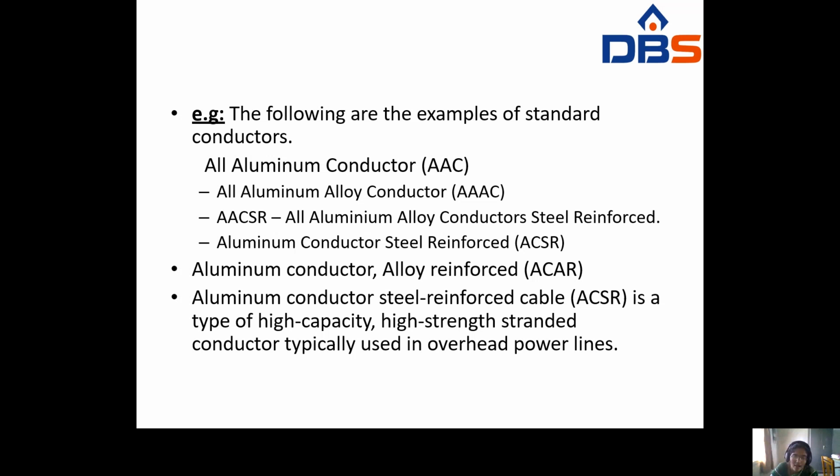AAAC, all aluminum alloy conductor. Next one is aluminum conductor steel reinforced, ACSR. Next one is aluminum conductor alloy reinforced, ACAR. Aluminum conductor steel reinforced cable, that is ACSR, is a type of high capacity, high strength stranded conductor typically used in overhead power lines.